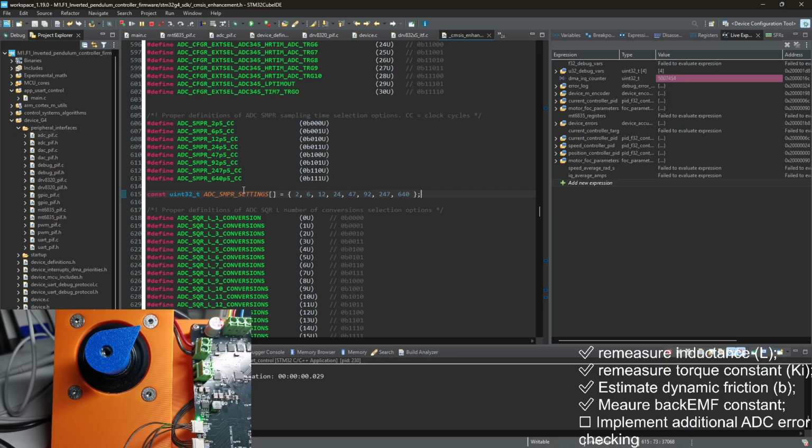And for braking, when you brake using a brake resistor, it's completely independent. You just measure the voltage on your bus, and if the voltage is higher, you start opening the braking transistor, so that the power from the power supply and from your motor that is working as a generator can flow into the resistor to dissipate as heat. So this is a completely separate thing that doesn't depend on what exact motor driver you use, if it makes sense.